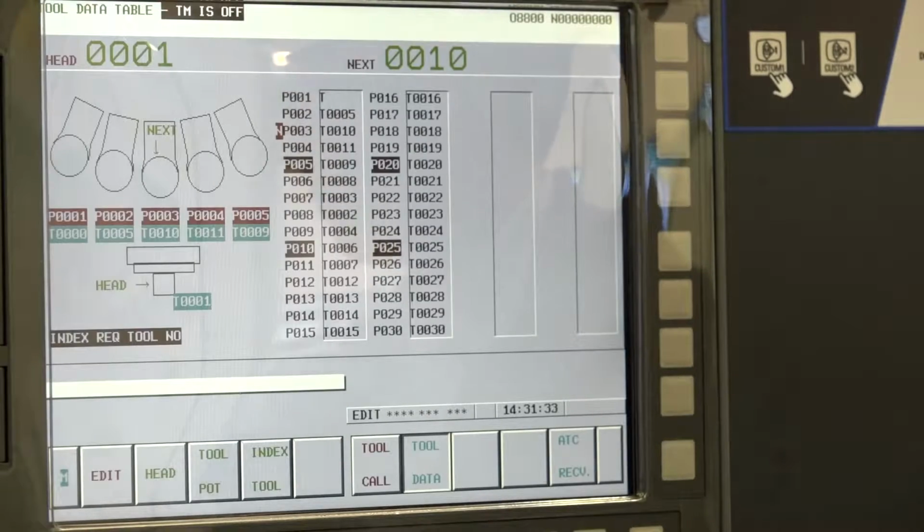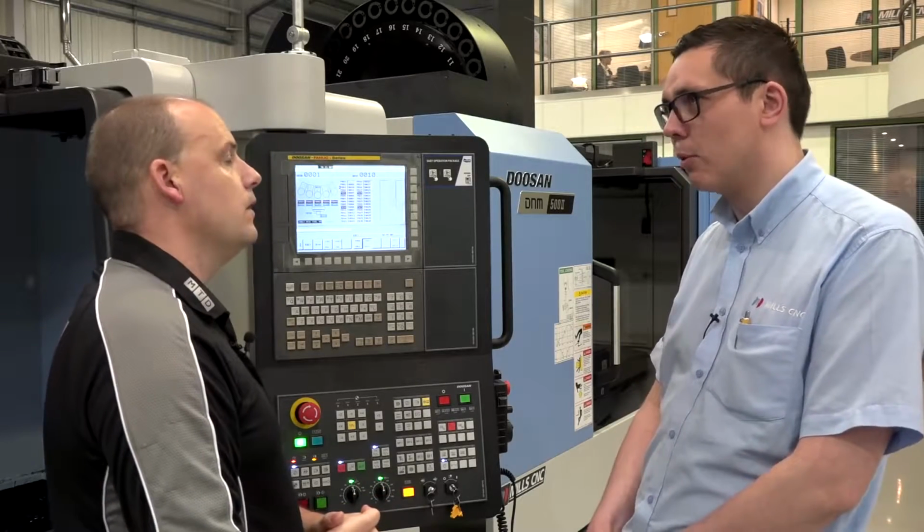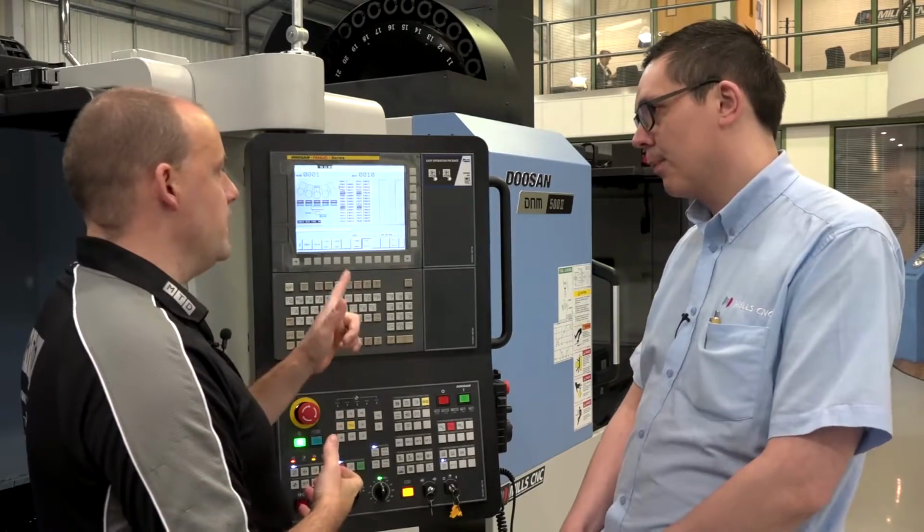A tool ribbon. So this will have things like the tool data, pockets, tool numbers matching up, oversized tools, putting that in. And before you had this EOP system, how would you have done things like this? You'd have to do a double M6 and then be mindful that the pockets adjacent to that are not to be used. And there's also the tool recovery.